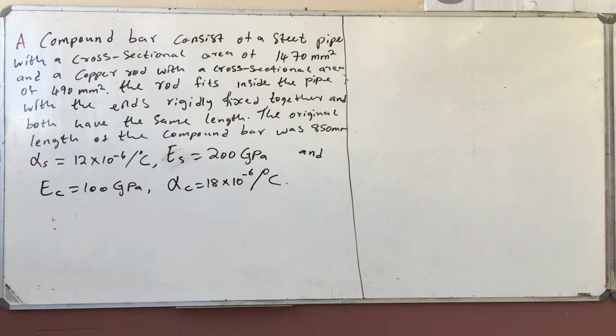When we look at the coefficients of expansion between copper and steel, which one will expand more? It's copper, right? And what will be the nature of stress in copper? Compressive. Yes, that will be compressive.